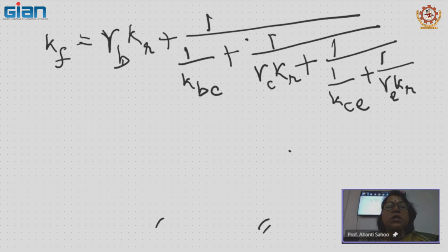So, reaction takes place in the different phases. When one calculates the overall reaction rate in the reactor, one does not calculate only how much is bubble to cloud. That we calculate separately, and finally we add all the things. So, emulsion, then cloud to emulsion, whatever movement is there across the boundary, then in the cloud also some reaction takes place, and bubble to cloud, and then in the bubble also.